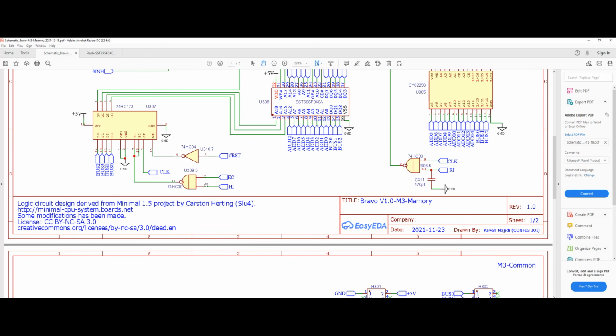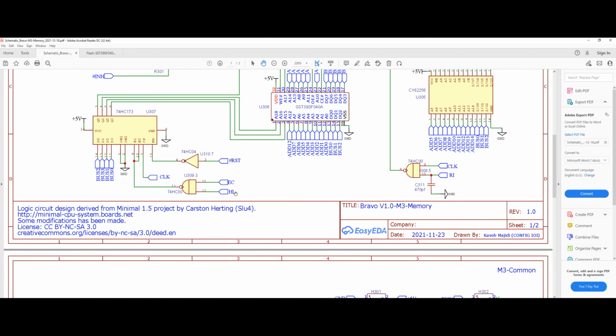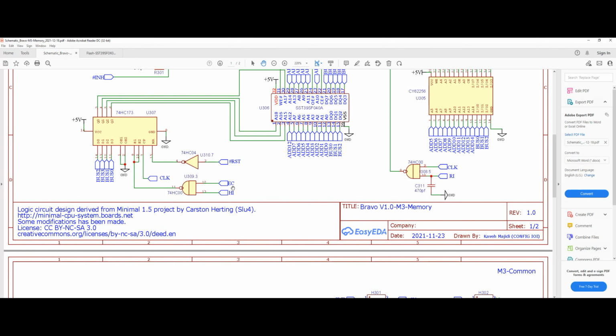However, if you look at the circuit, we are actually combining two other signals through a NAND gate in order to make that specific control signal. And those two signals are EC and HI. By now, you should probably be familiar with both of these signals because we talked about them in the previous videos. For example, EC is one of the signals that we were using in our ALU circuit to add 1 when we were making the 2's complement.